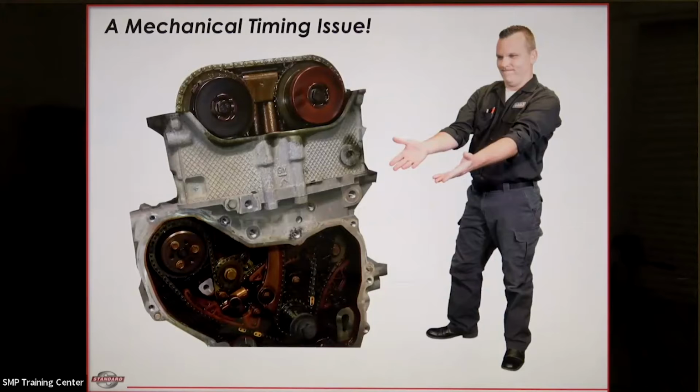So in this case, it was all related back to the fact that the engine had jumped time. That P0016 was actually telling us what was wrong. We have a timing problem, a base engine timing problem. So we need a timing chain set. So we really need to understand the interrelationship between the mechanical timing of the camshaft and the high pressure fuel pump that it's driving.